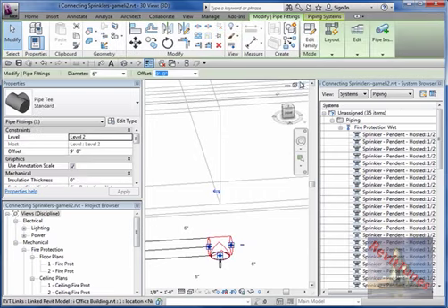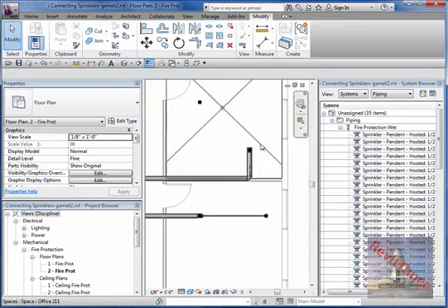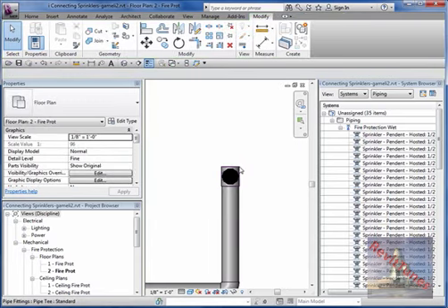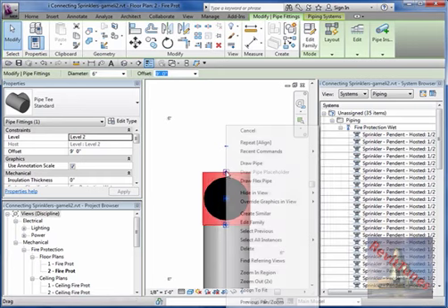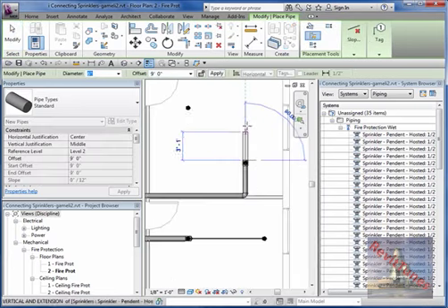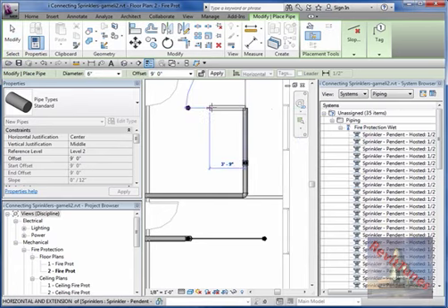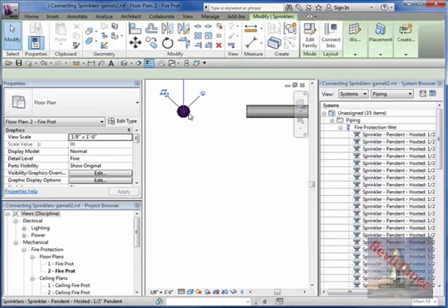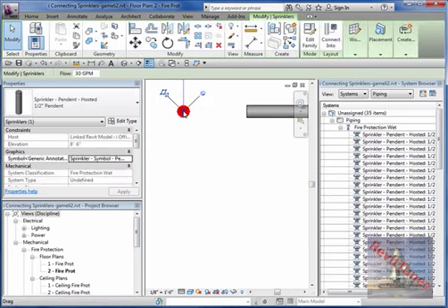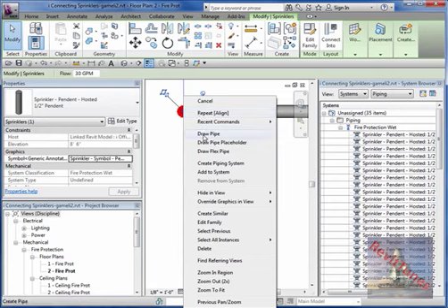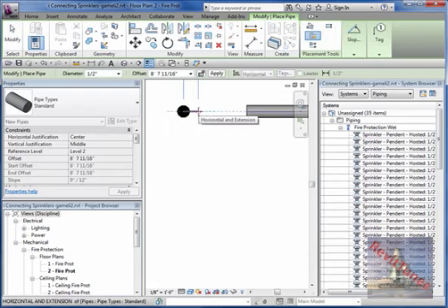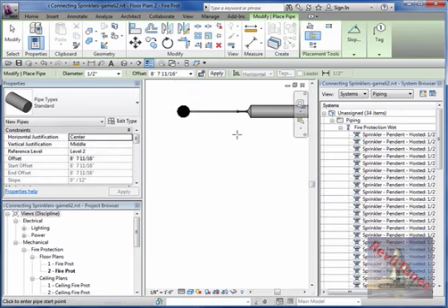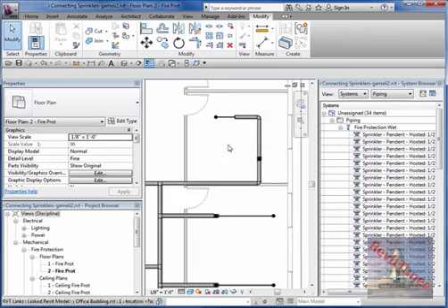Okay, so I will close the 3D view. I have my T. I touch it. Now I have a connector here. Draw a pipe. Again, I hold Shift, so it's ortho, and one more ortho. And I don't want to touch yet. Now I select the sprinkler, right click on top of the connector, draw a pipe, hit tab, so I grab the height of this, and now click on the other connector and this funky connection right here.